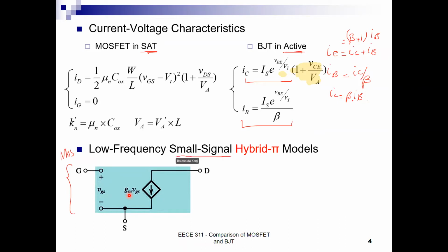Above, we said these are DC. Corresponding to it, if I have an early voltage effect, meaning a slope here, then I add a resistor RO in the equivalent model. Many times in the analysis we tell you to ignore RO in DC, meaning calculate the current equation without it, but consider it in the small signal analysis.